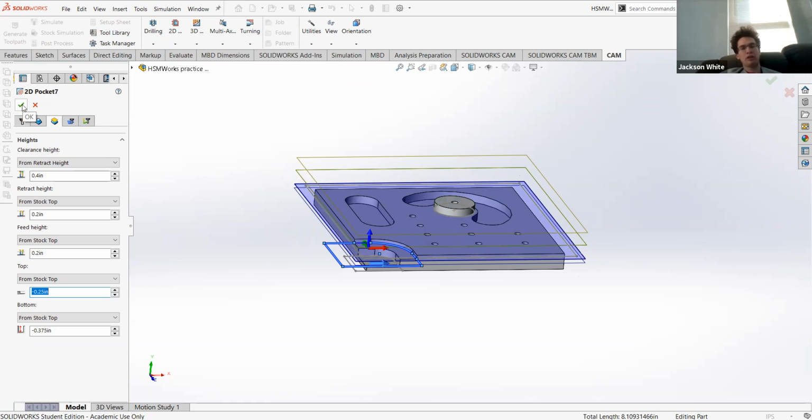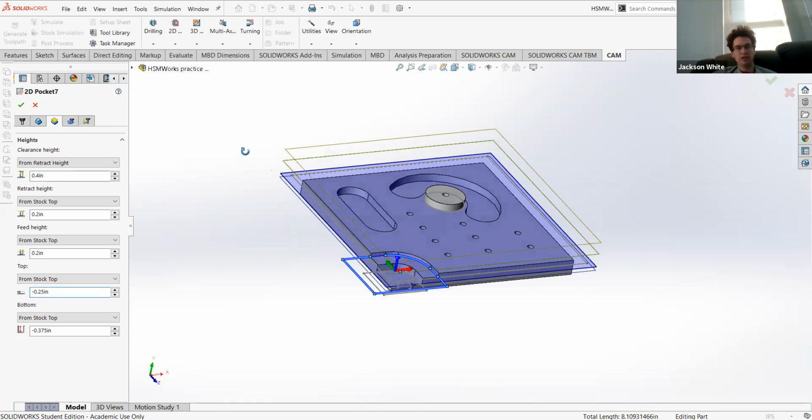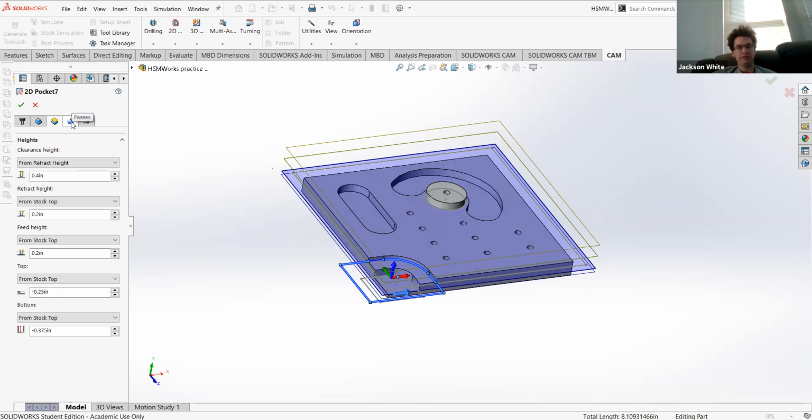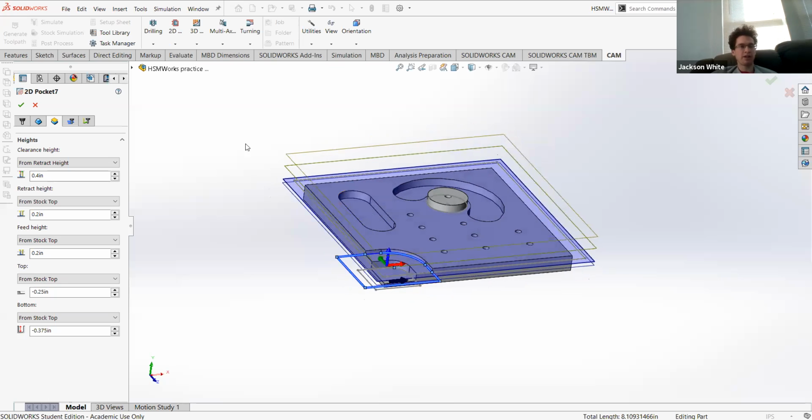And the thing to maybe worry about a little bit here is, if you ever rearrange the tools, you have to make sure that the stock top is the top of this operation and is not embedded in the stock already, or else it will think it can just plunge the end mill directly into it, and then things will break and you will be sad.